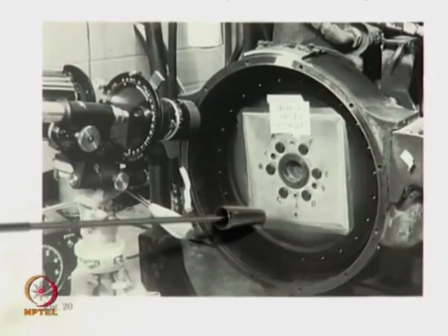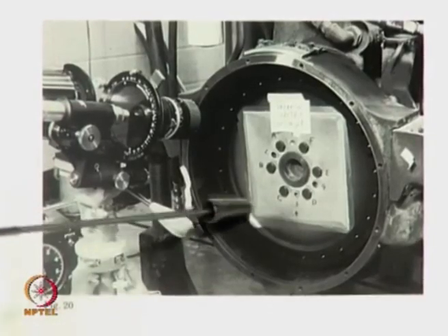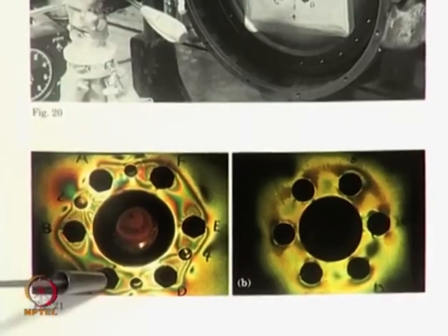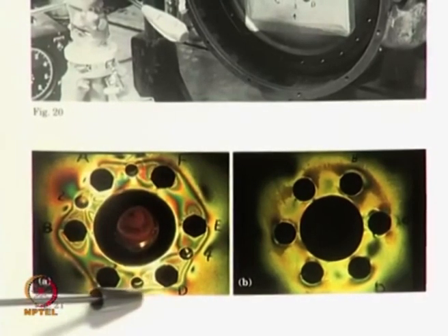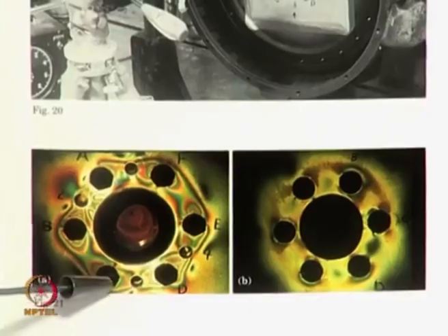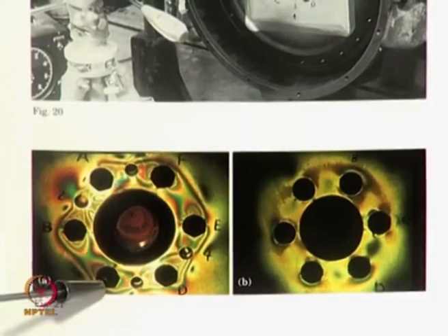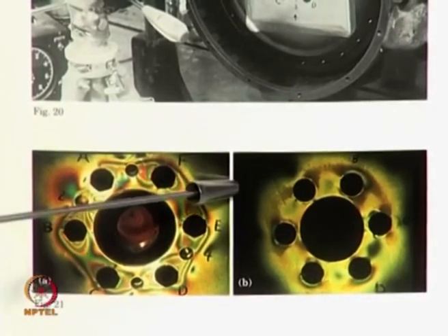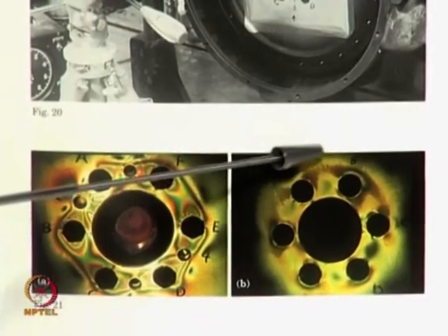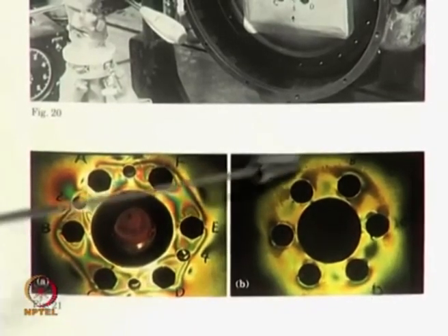This shows another example of application of photoelastic coatings. Here you have a flywheel that is being analyzed. I had mentioned that when you see colors in a photoelastic coating test, you have to be worried, that indicates the stress levels are very high, and this is the initial design of the flywheel, and these are the stresses due to assembly. Based on this input, when the design is modified, you have the final set of assembly fringe patterns, which are very good from design point of view.